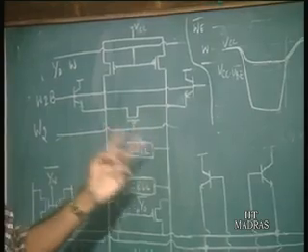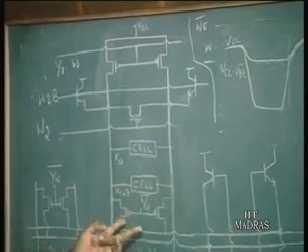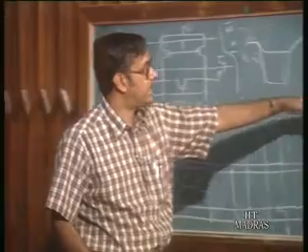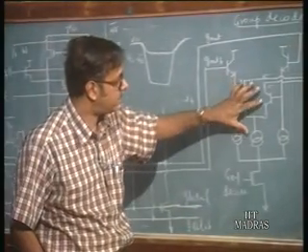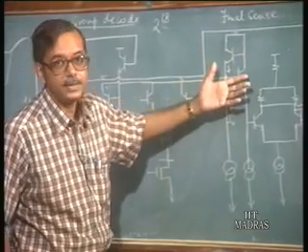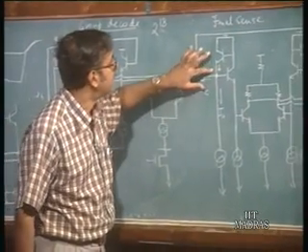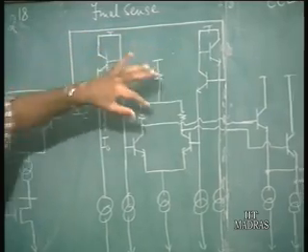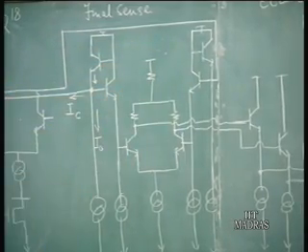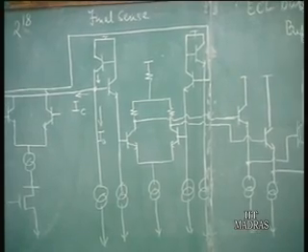Only a small difference voltage, 90 millivolts, is created, and that makes it so fast. Then this 90 millivolts is fed to the base of a differential amplifier, which creates a difference current, which is then sensed, creating a difference in VBE of the 2 transistors, which is finally sensed and again converted to ECL level.